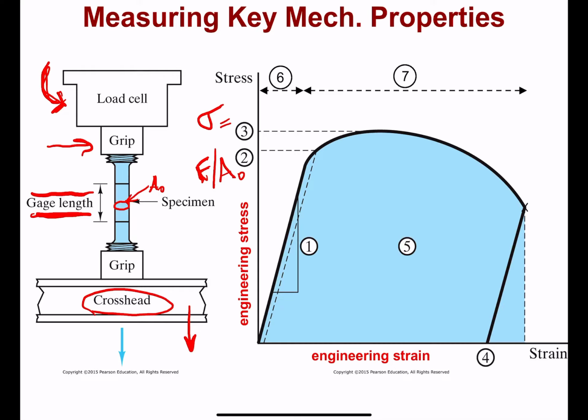And of course, some deformation is going to occur. So we're going to extend the object from its original length. That could be represented here by the gauge length portion. So we may have L, and if it's under no load, we can give it L naught, some original length. As we apply increasing amounts of force, we'd expect the gauge length to enlarge.